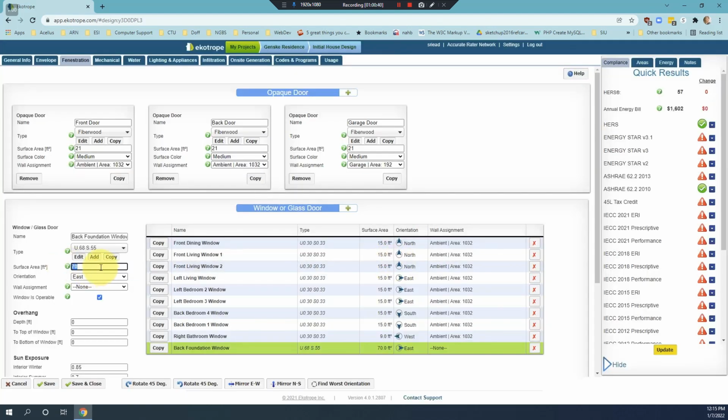The surface area of these windows, let's see, on the plans they show 32 by 16 glass block. Now that could be 3 foot 2 inches by 1 foot 6 inches, or 32 inches by 16 inches. The nomenclature is different than on the main level, and usually the nomenclature on all the levels for the windows will match, and sometimes it'll be written on the plans showing you whether those numbers are feet and inches or just inches. So I measured this window with my architecture ruler on the scale drawing, and it is 32 inches